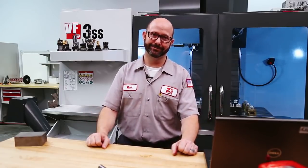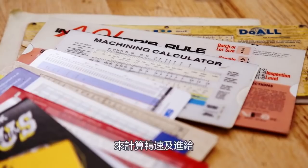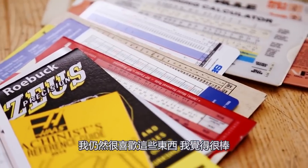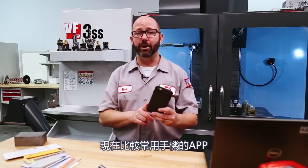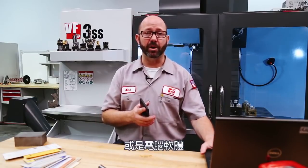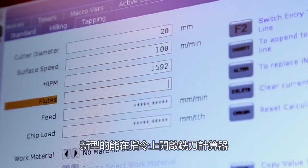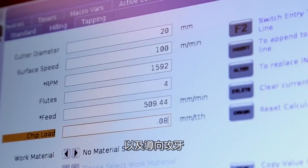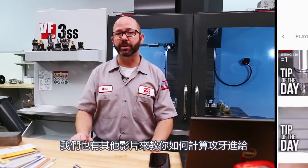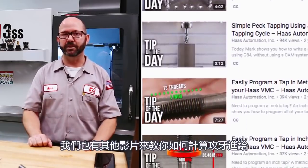You may open up your manual and find that you don't have to do any math at all. Okay. In the past, we used to have to rely on slide rules to calculate our RPM and feed rate. I still like these, I think they're great. But today, we're more likely to use an app on our phone or a piece of software on our computer, or the speeds and feeds calculator right on the Haas control. On machines with next-gen controls, you can reach the milling calculator by pressing current commands and navigating to the milling tab. We've made some videos that help you calculate those tapping feed rates. We'll link to those in the description.